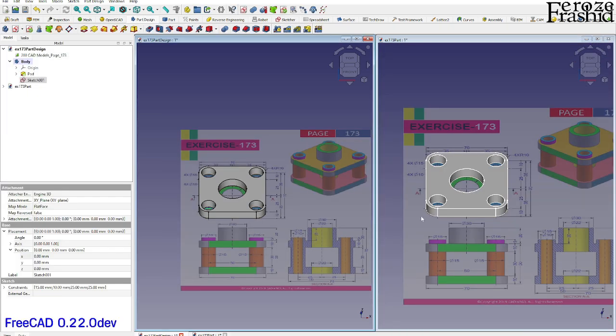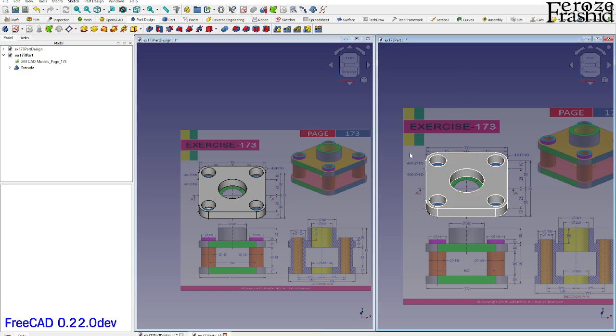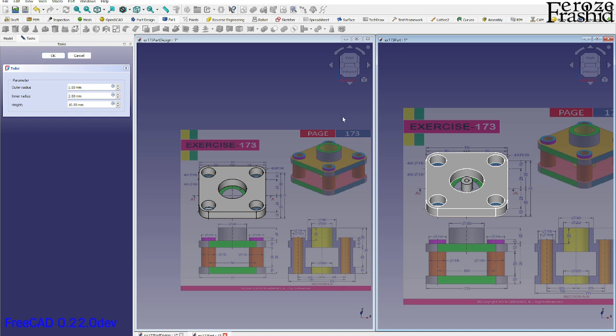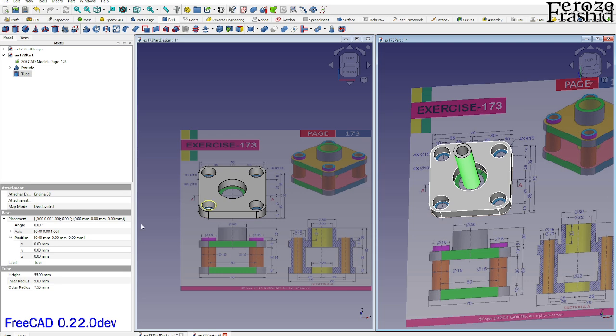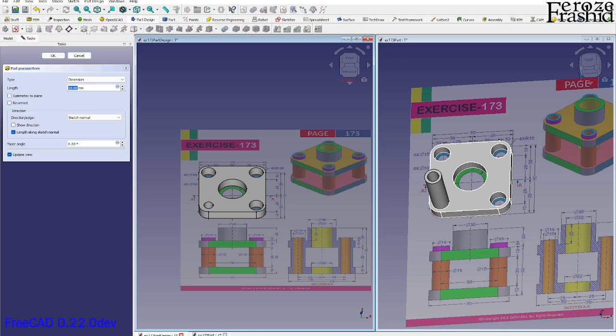That should be fine. All right, and I can take that and paste it in the Part workbench as well, or in Part, which I like most is the primitives. I can build a primitive tube. So it would be outer radius 7.5, which is diameter 15, and inner diameter 10, and then I can build the height at the same time. That is one good thing about Part primitives. I think we flipped each other, so it would be 5 there. So we got that, and the next thing is to adjust the x and y, which was -25 and -25. So there. And in Part Design, we pad that up to 55.